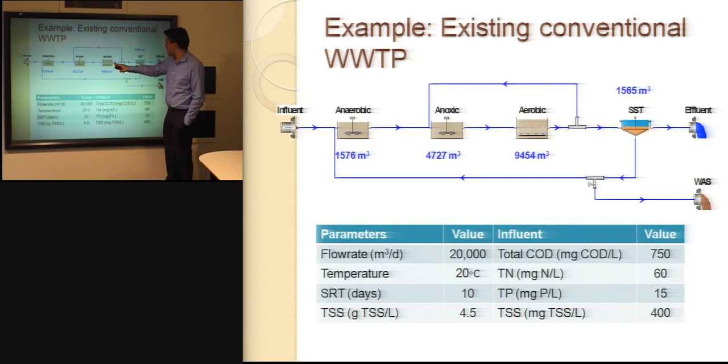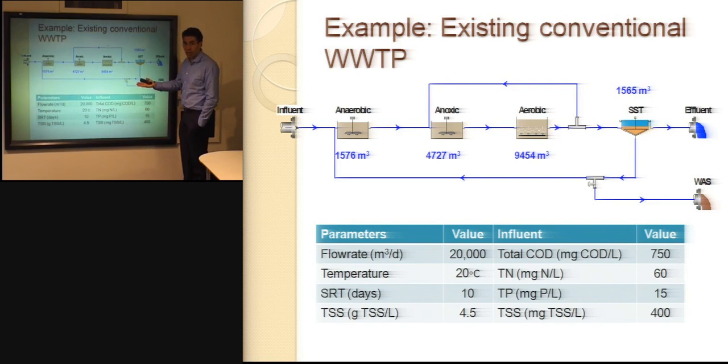Once the organics, the nitrogen compounds, and the phosphorus are removed by the microorganisms, leading to the growth of more biomass, the biomass is settled in a secondary settling tank to have a treated effluent that will flow clean out of the wastewater treatment plant.